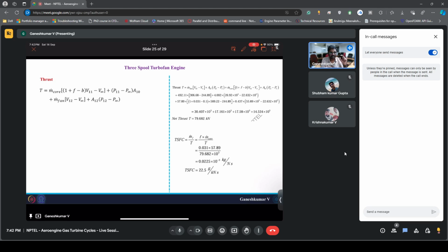However, our exit area has increased, so between this increase and decrease there might be some mismatch, but the stronger effect is that m dot core has decreased. Okay, or the m dot exit has decreased. That is the main thing. M dot exit has decreased, and v exit also has decreased, at least in the core region. But in the bypass there is no change.